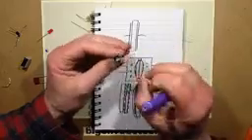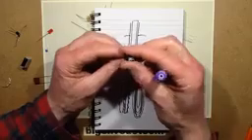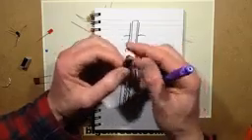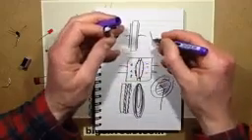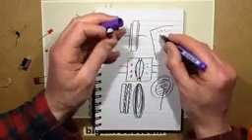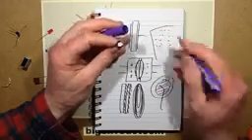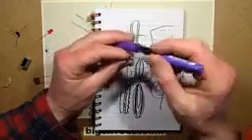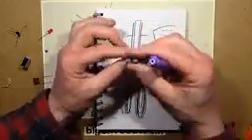And that means it really is like micron thick, which means that they can get a very high capacitance in a small area. But to couple onto that surface, they have to use a liquid electrolyte, because if you looked at the foil, it would look all pitted and mottled with that oxide coating. So to get a good coupling, they use a liquid that just fills in those gaps. And that's one of the downsides, well, it's many of the downsides of the electrolytic capacitor.